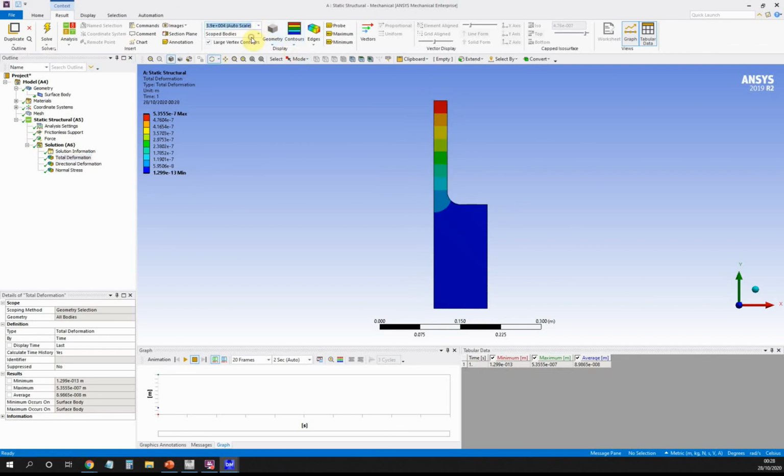If I put that to true scale, they're exactly the same. If I put it up to twice the auto scale, you can see it's very much exaggerated. Or it could even go 5 times the auto scale. Remember, the auto scale is just there to give you a bit of visualization to help you see what's actually happening. So really, true scale or the auto scale is useful sometimes. Again, the auto scale is showing me that it's expanded a bit up that way. So again, I can just go back to no wireframe or show elements, which is the usual one.